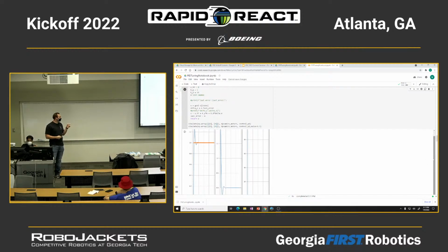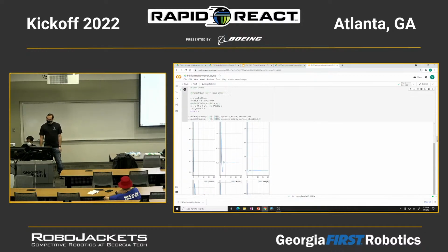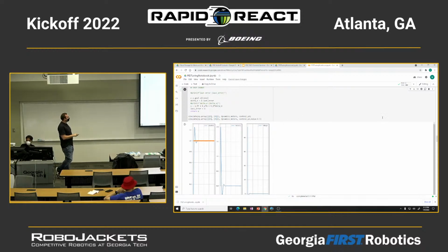It would be hard to get something that looks like this, because you see we essentially immediately jump to our set point, and then we stabilize there really quickly. I'm cheating here because there's no actuator limits, so we can command infinite velocity. The voltage spikes up to over 80. What does that mean on your robot? Brown out. Yeah. Since you guys have 12-volt motors and 12-volt batteries, you cannot ask the motor controller to give more than 12 volts because the power source is only 12 volts. So that's where the actuator limit comes into play in your real-life robot.